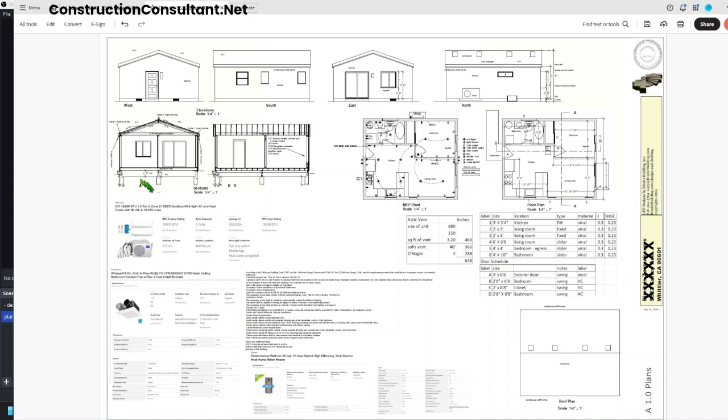Now you see these are AA and BB. You would go back to this drawing here where it says AA, and now this drawing is looking to the right here into what the building would look like. Same thing with B. With B, you'd be looking straight up, and that's what this view will look like.